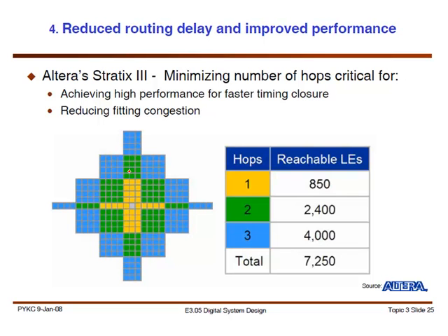Now, this is interesting, especially for the group who are doing the analytic placement for FPGAs. One of the things that they think about when they design the routing structure is how much delay you would have to incur to connect a logic block to another logic block, let's say 10 horizontal units to the right and 3 vertical units going up, how much delay you have to go through, how many hops do you have to go through, how many of these switch boxes you have to go through.